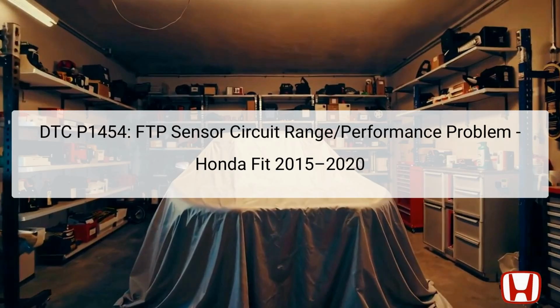Depending on the design of the Honda Fit from 2015 to 2020, when the FTP sensor fails to deliver the expected voltage or pressure readings, it can lead to increased emissions and potential performance issues. It's essential to address this DTC promptly to maintain vehicle efficiency and compliance with environmental standards. This troubleshooting guide will help identify and resolve the underlying issue related to DTC P1454.